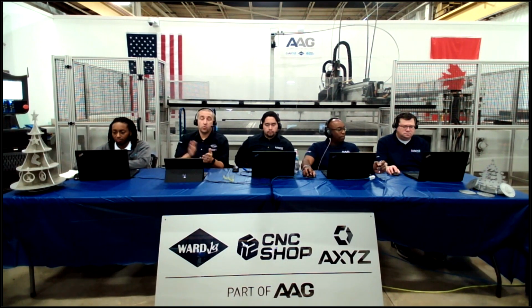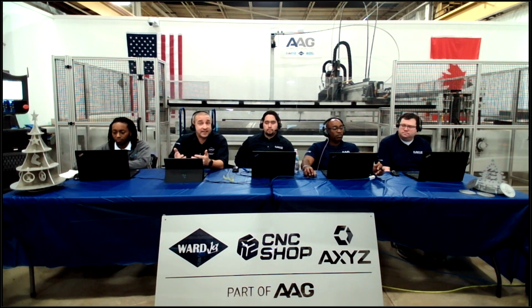So WARDJet is unique in that we do have a specialized line of product that is designed specifically for water-only cutting. The main tenet of that design is going to be our dry tank system. Instead of having water in the tank to dissipate the stream, we have a sloped, full stainless steel bottom tank, able to let some of the smaller debris you get with foam and rubbers go. If you're cutting that in water, it'll turn into almost like a scum or floating debris on the water. If you're using a standard machine, you've got to raise the water, skim the level, and then that of course equates to lost production time.